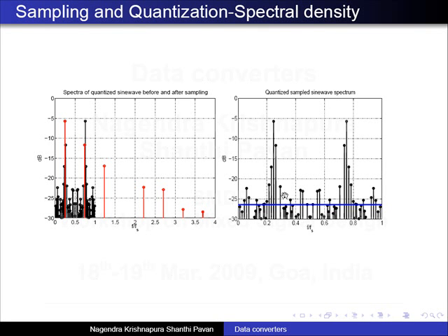So you can see it varies a lot around the average, but this is the average, and we'll use that average number later. So is this clear what the spectrum of the quantization error looks like? This is very important if you have to simulate or test A to D converters, to know what to expect. When you simulate it, if you put in a sine wave, you will see all these other tones, and that is quantization noise, and that's how they come about. Any questions so far?